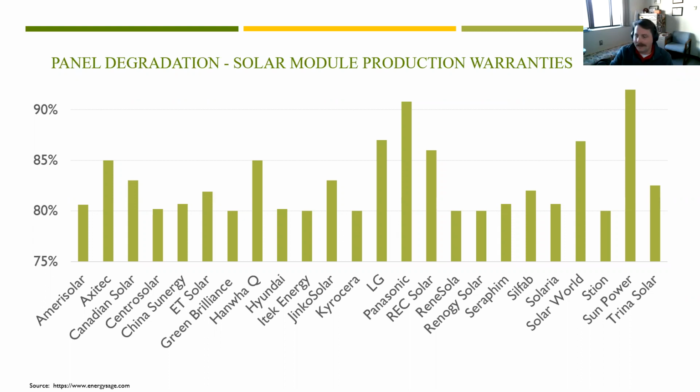They have decided that a solar panel is, I don't know, you'd say worn out when it has degraded 20%, or it's putting out 80% of what it did when it was brand new under standard test conditions. And so they have built solar panels that generally meet or exceed that degradation level of 20%, or 80% after 25 years.